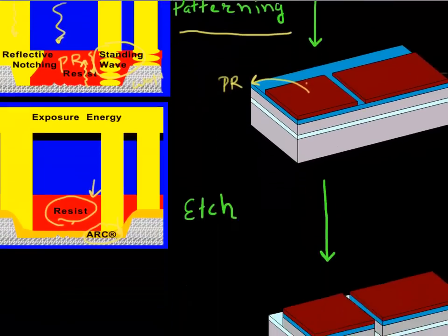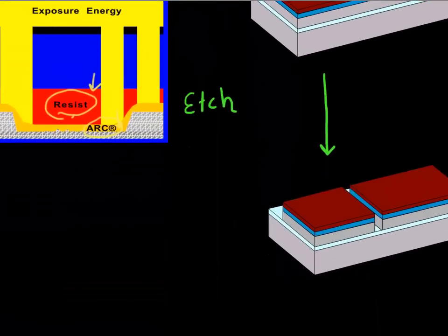The next step involved is essentially we etch this pattern into first our nitride, and then use that nitride as the hard mask, because it's a harder material as compared to photoresist, to etch that feature into our silicon.